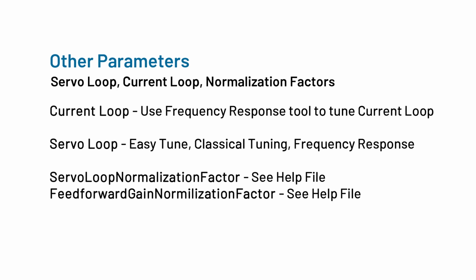Next is the servo loop. Tuning from scratch on the servo loop, however, will require a little more determination on some other secondary parameters. These will be the servo loop gain and feed forward gain normalization factor parameters. Then after we figure out what those should be, you can either use EasyTune, classical tuning, or the frequency response tools to tune your stage or motor. EasyTune is by far going to be the easiest method out of the three for doing this.